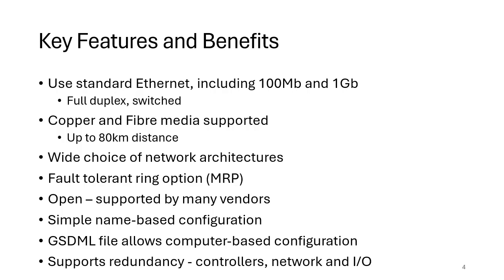Now, PROFINET is open, it's supported by many vendors, tends to be more European. Certainly it was originally developed by Siemens, who are a European manufacturer, but many other vendors have now taken up PROFINET. And as it's an open protocol, you no longer have to go to Siemens for the chips. That was one of the issues in the very early days of PROFINET, but that quickly went away as other people came along and allowed you to implement the protocol using either their software stack on the standard Ethernet device, or you could buy dedicated chips from multiple vendors. So very open, and supported by multiple vendors.